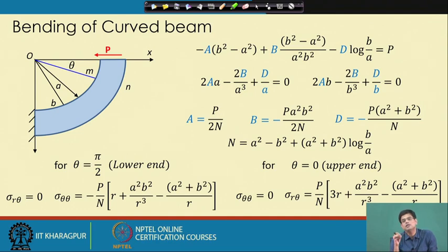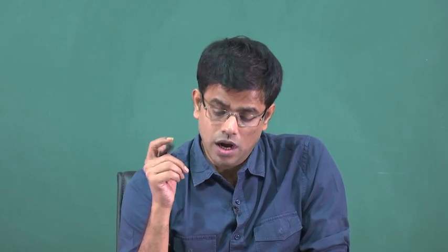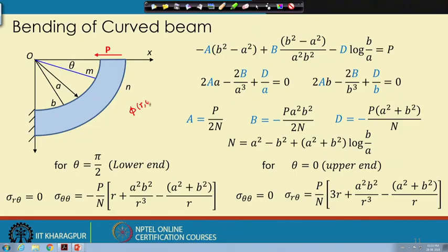Now, while approximating the stress function here, we used our intuitive knowledge of strength of materials, where we essentially use the separation of variables, where phi, a function of r and theta, can be written as f of r sin theta. Instead of sin theta, you can also use cos theta if there is a couple, which will give you the solution.